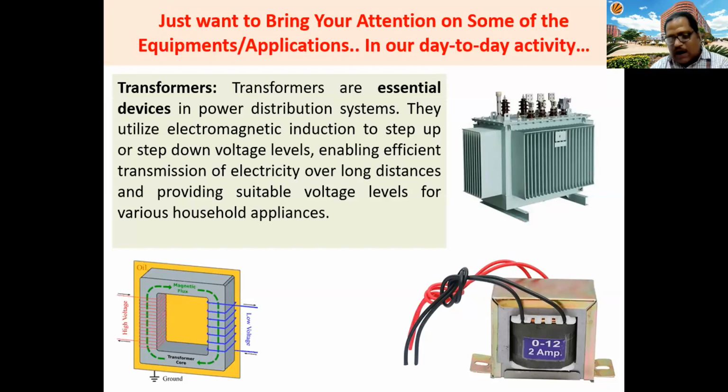So this is interacting with this blue winding, the secondary winding. Here EMF will be induced with the concept of mutual induction. And the same flux is going to produce an EMF in its own winding also. So this is what you can say self-induction is happening.